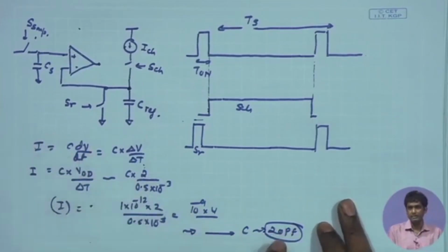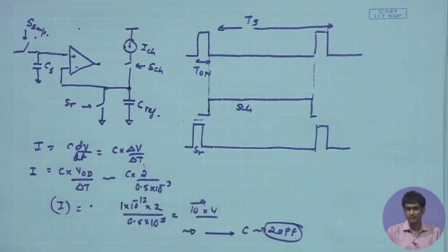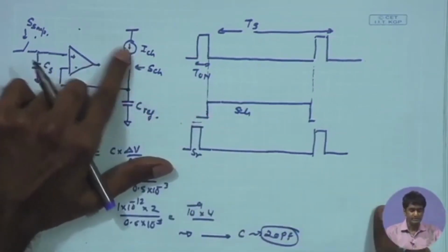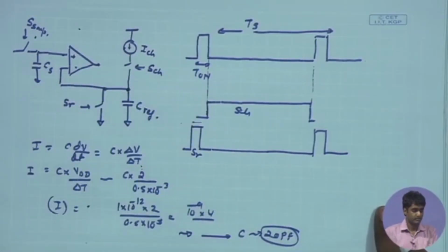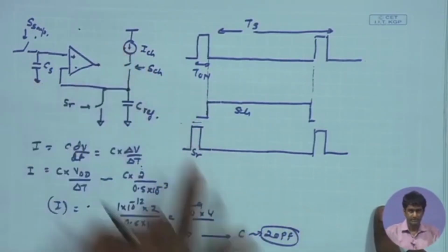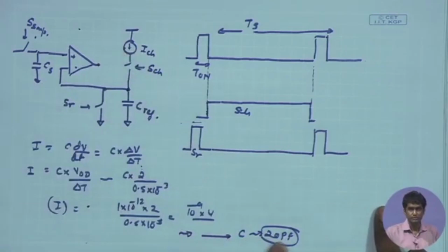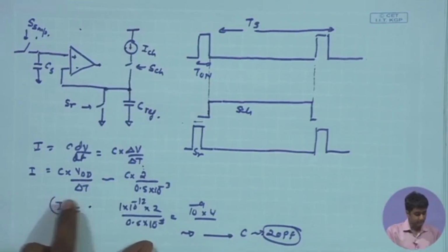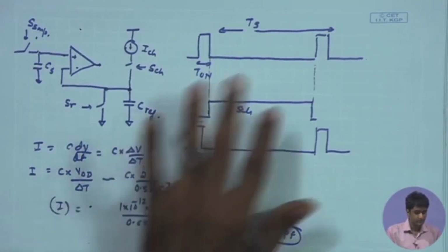Remember, in the front end amplifier, we had limited our capacitances to 10 picofarad and lower. But once again here in the ADC, the requirement to keep these currents sufficiently robust over process and temperature forces us to have a C value which is larger. Of course, another constraint is also coming from the delta T, or the sampling frequency.